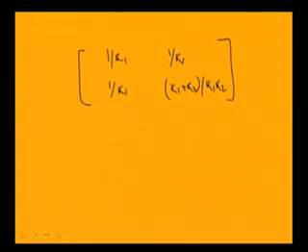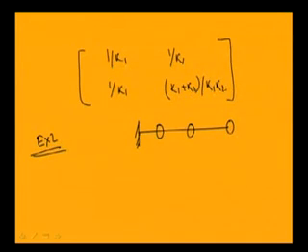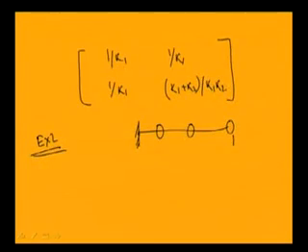So let me take another example to find the influence coefficient. Let me take a simple cantilever beam. In this cantilever beam, let I have 3 masses attached. In this case I have to find the influence coefficient. Let me find A11. Let this be position 1, this position 2 and this position 3.